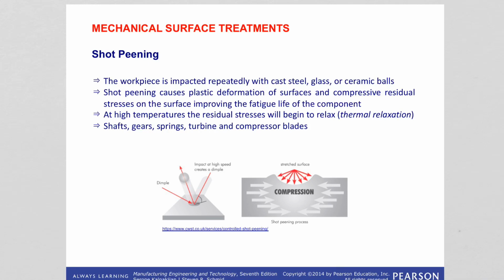This technique is applied to gears, shafts, turbine blades, connecting rods, engine blocks, compressor blades, and springs, just to enhance mechanical properties like increased fatigue resistance and resistance to stress corrosion cracking. So pretty much the lifetime of the part is prolonged with this technique. But you need to keep in mind that if we're gonna use this part at high temperatures, the stresses can relax and this technique can lose its effectiveness.